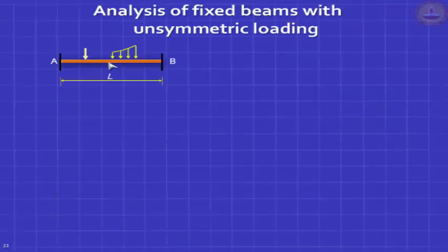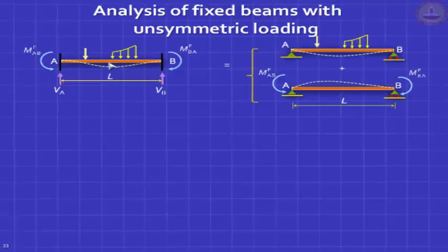Answer to your question: what happens if it's unsymmetric? Don't worry. Every problem has a solution. What do we do? First, break it up into a simple problem: a simply supported beam subjected to the unsymmetric loading, plus you have fixed end moments.